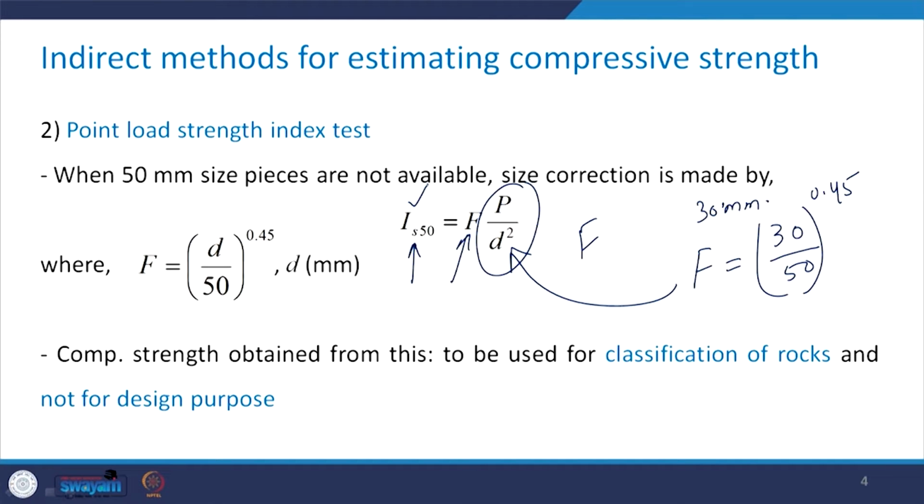Please keep in mind that the compressive strength that we obtained from the point load strength index test should not be used for design purposes.